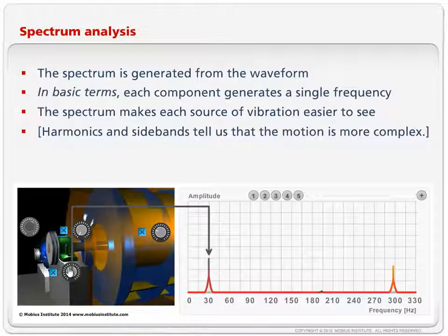It's not so much to do with criticality. Criticality tells us whether we can justify doing it. The PF interval, or the time to failure, tells us how often we should do tests.